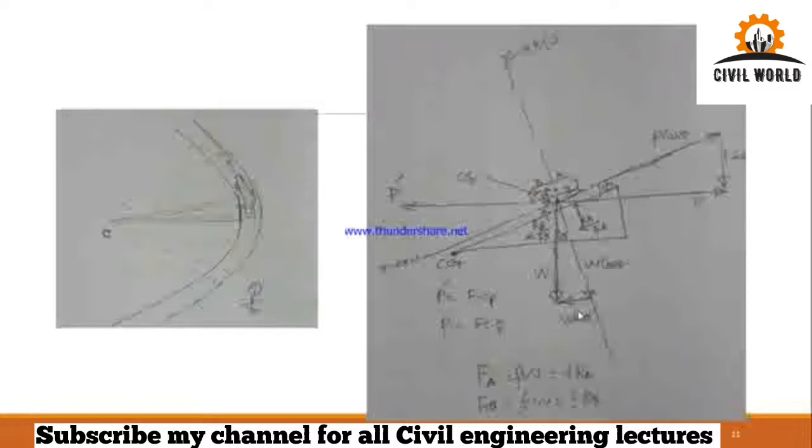These are the forces acting toward the right in the x direction, equal to the forces toward the left in the x direction, or the summation of the forces toward right is equal to the summation of forces toward left. Similarly, the summation of forces upward is equal to the summation of forces downward. So in this case, RA plus RB is equal to W cos theta plus P sin theta.